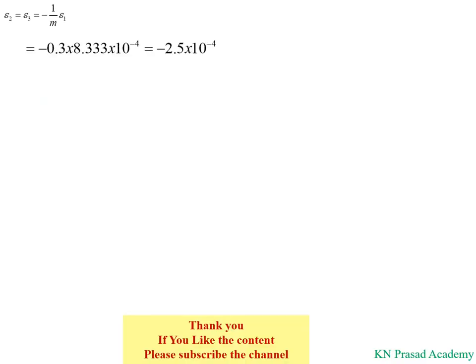Similarly, we have to calculate the lateral strains. We know the relationship between the lateral strain and the Poisson's ratio: epsilon 2 and epsilon 3 equal the minus of, why minus, meaning the opposite kind of strain will be produced. In the lateral direction we are applying tensile forces, so elongation takes place, but in the remaining two directions, the width and thickness, contraction takes place.